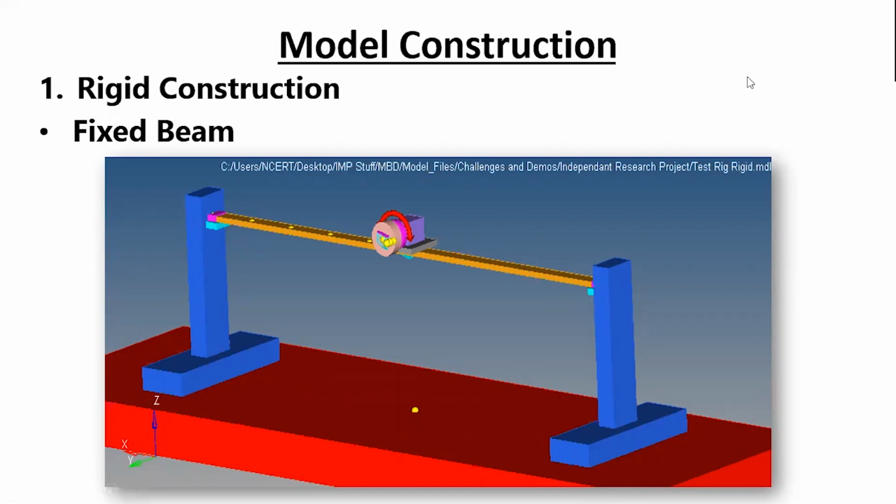The second thing is that even if the total degree of freedom of the system is greater than or equal to 0, this problem happens. So to ensure that we are able to calculate reaction forces on both the joints, I have made use of planar joints. Now, planar joints, what that means is that in this case, the planar joints have been oriented with respect to the z-axis. This means that this joint can move anywhere in the xy plane.